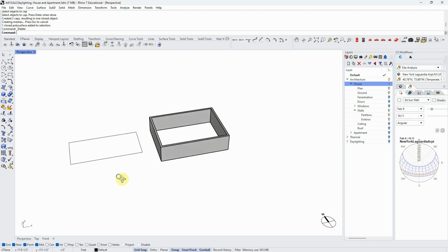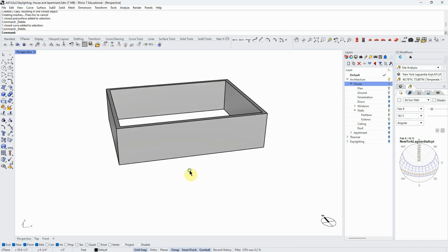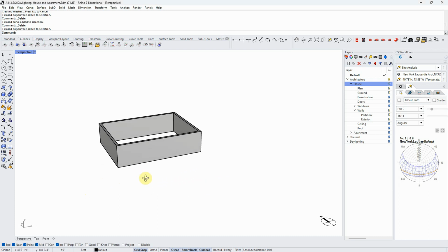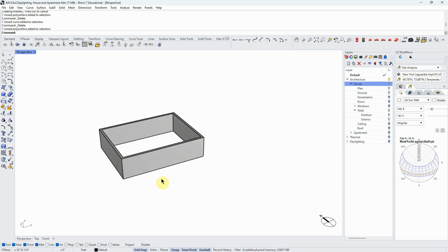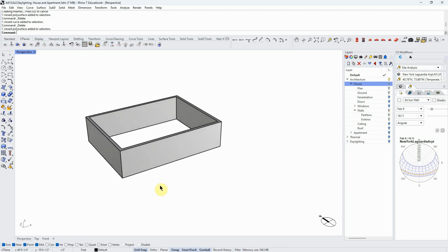All right. So anyway, let's say we want to put windows now into these walls, and for daylighting we need to have punched windows, which basically means we need holes, either if it's a surface or a volume, we need to have a hole cut through it in order for light to go through it. That's again going to be different in the thermal simulation, so that's why we're going through these things, to learn these idiosyncrasies. So how would I poke a hole in this wall easily?